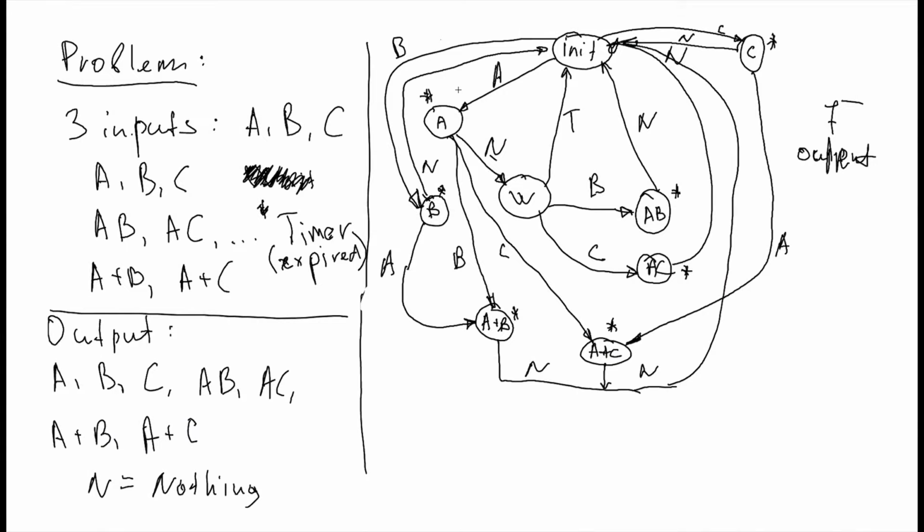And then we encoded our inputs, and then we introduced encoding for the states, and then input encoder, excitation function, output encoder. The only thing that we probably have missed is one optimization step that combines design of the excitation function with the design of the input encoder.